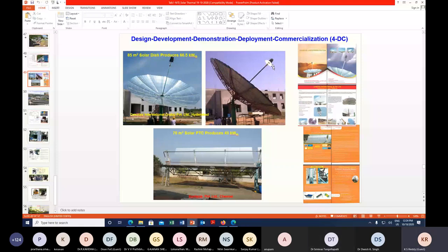h can be either convective or radiative, any heat transfer coefficient. Delta T is higher, isn't it? The ambient temperature we cannot control, but we can raise the temperature T1 very high. But when we increase T high, it will lose heat to the atmosphere through either the area or the heat transfer coefficient. So if we reduce the area, we can reduce the heat losses, or we can also minimize the heat transfer coefficient. Therefore, these are the challenges.